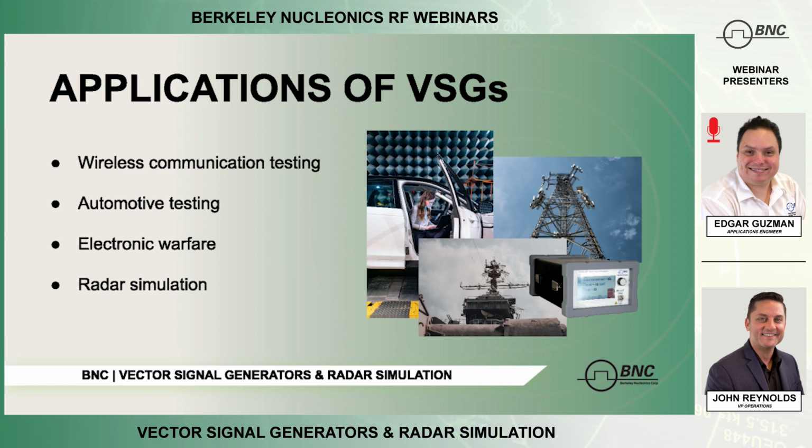Wireless testing, obviously, you want to test how well your receiver is going to respond to noise and environmental radiation, such as a cell phone next to your Wi-Fi router. Like, how do you know how it's actually going to react? Is it going to drop signal? Because I know wireless Wi-Fi signals are usually at 2.4, 5, and now 7 gigahertz. So you're able to test or simulate different effects on your system using a VSG to test out the different aspects of your wireless communication systems.